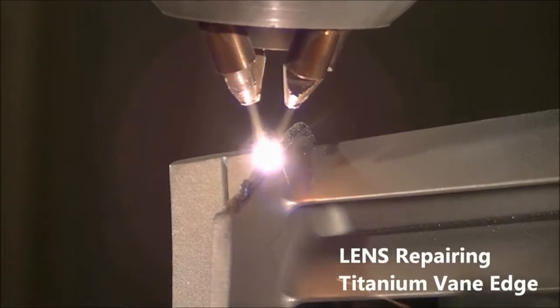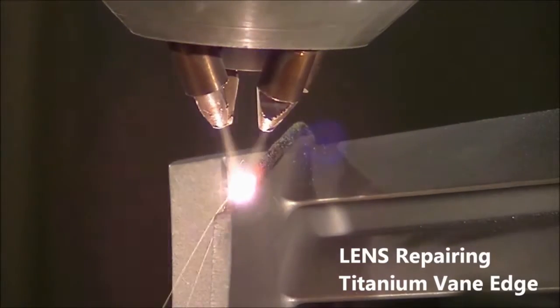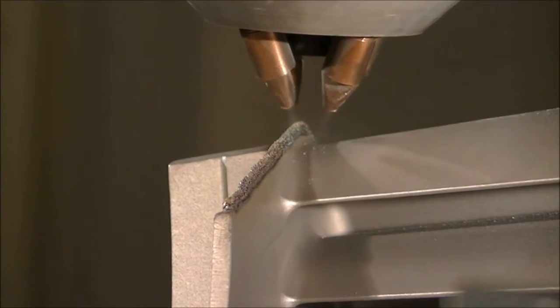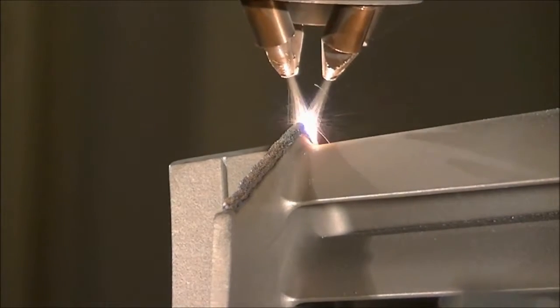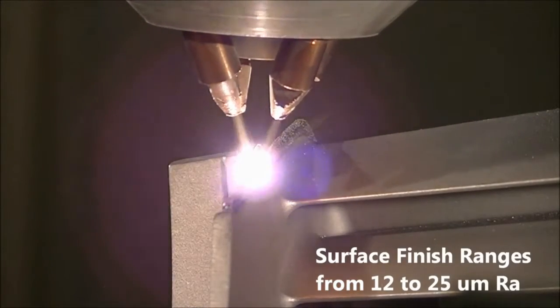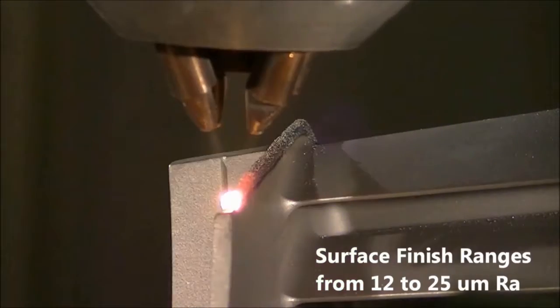The lens technology is applied to various industrial use cases. Using the advantages of the process, a thin titanium edge part can be repaired using additive manufacturing. The achieved surface finish reaches up to 12 micrometers Ra.